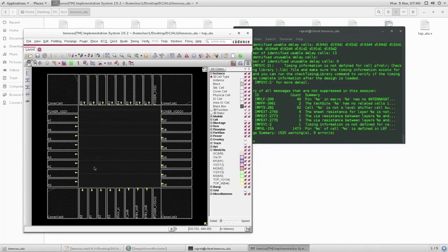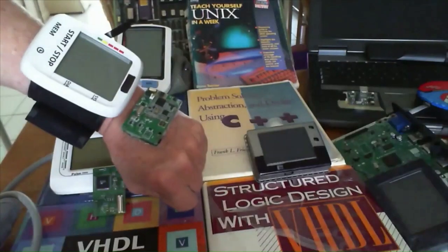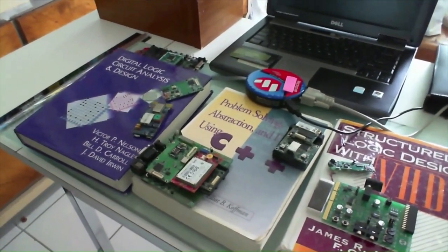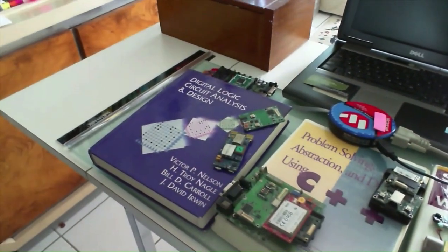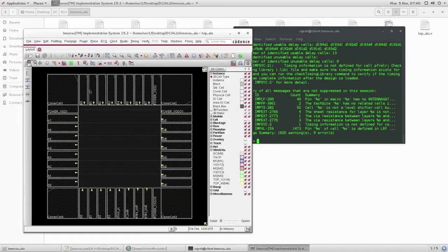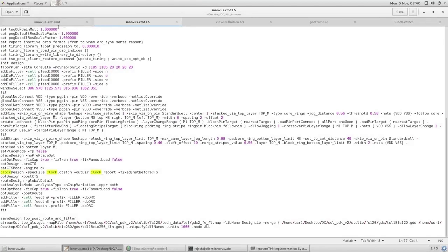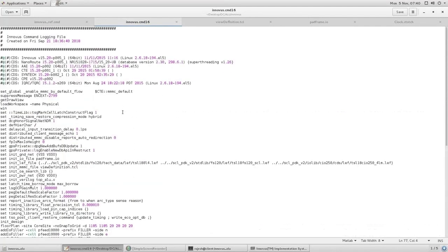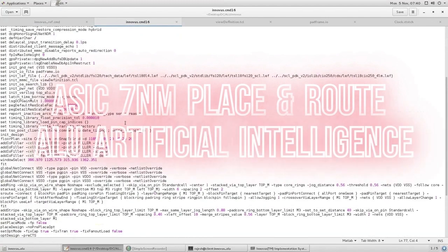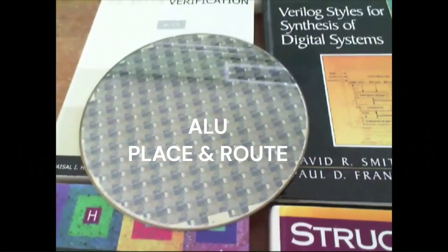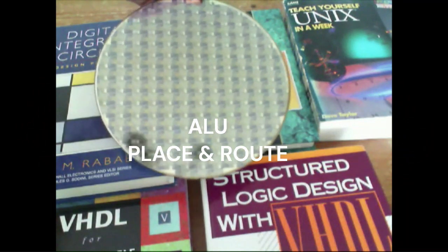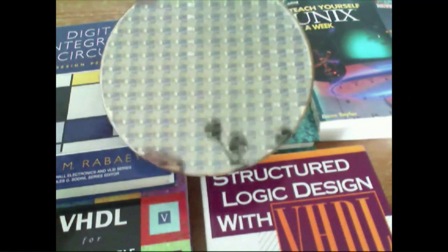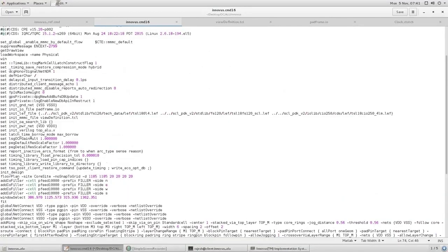Two, generate constraints for placement on the basis of a timing analysis done using idealized clock arrival times at latches and estimates of wire load and RC delay before physical design. Three, perform an initial placement to determine an improved basis for constraint generation and optionally to fix the placement of large objects.